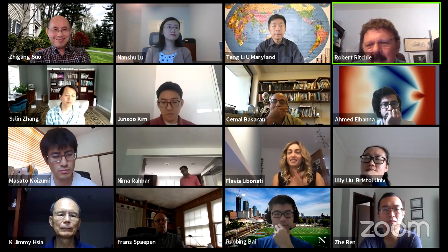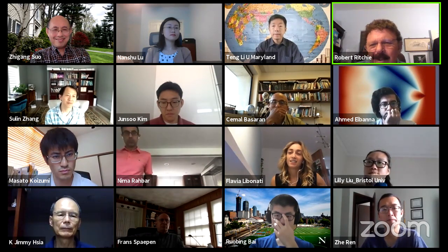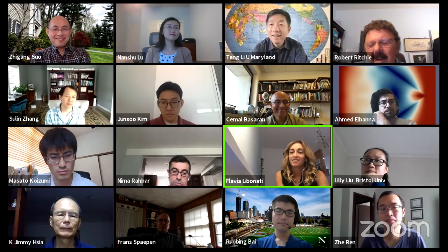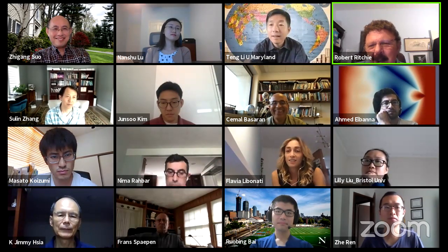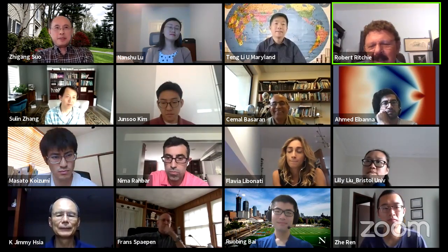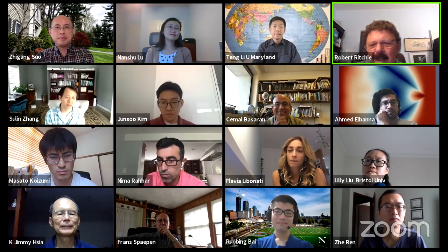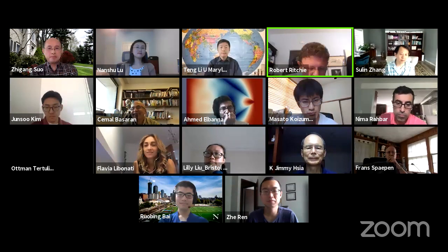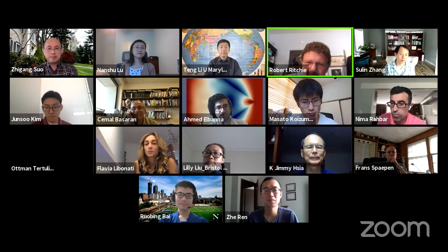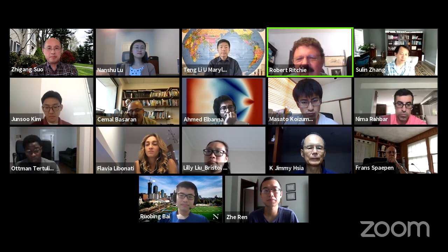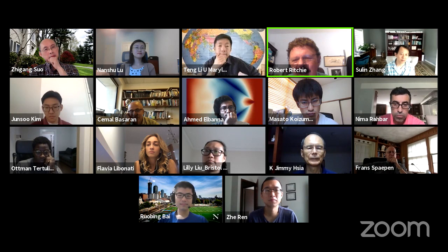Yeah, that's great. But the problem with MD is, do you have good atomic potentials for this? I mean, you're dealing with very, very high strain rates with MD, right? In comparison. And you're looking at what, cubic picometers or something like that. So there's quite a lot of problem, I think, with that at times. Anyway, I've started to use MD for these high entropy alloys. I don't do it myself, but I think it tells you something. But you've got to be very careful, because it's not so close to reality as we'd like.